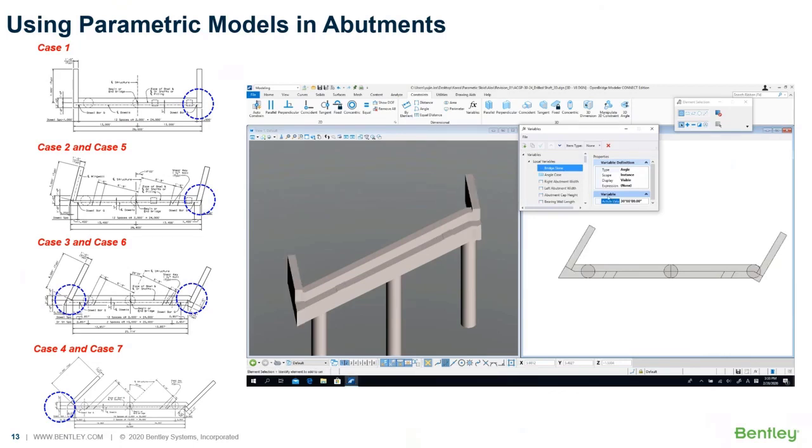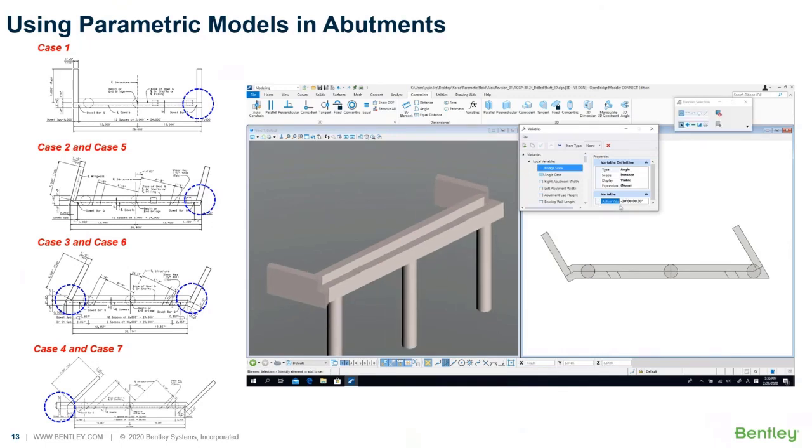The corner block shape had to be changed by condition where the bridge skew angle was 0, more than 0 to 15 below, 15 to 25 below, 25 to 45 below, and more than 45 degrees. And then you can see each different shape due to skew angle.